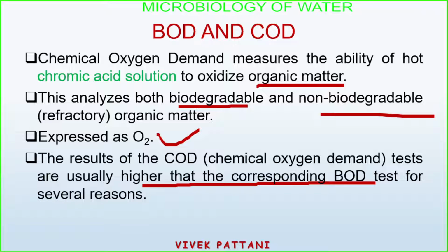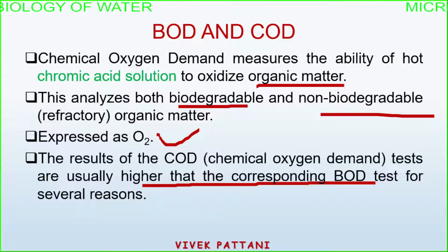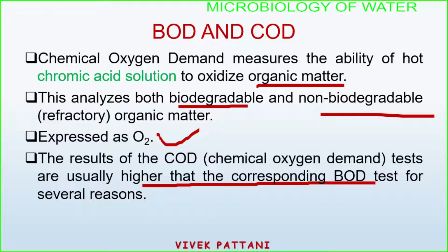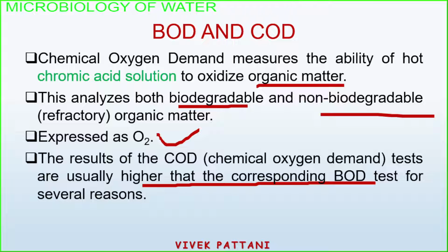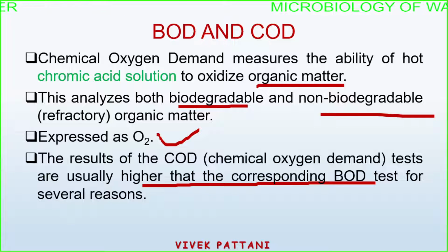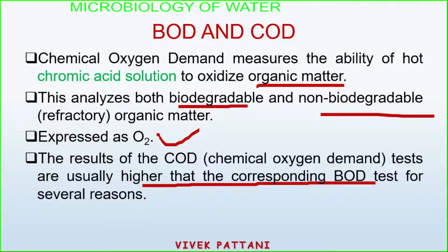Sometimes certain inorganic substances such as sulfates, nitrites, and ferrocyanides are oxidized by dichromate, creating an inorganic COD, which may sometimes be misleading when estimating the organic content of the wastewater. Now, for example, in the case of BOD, the BOD value for glucose or